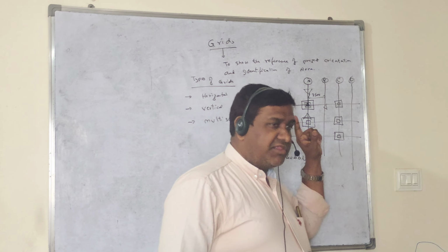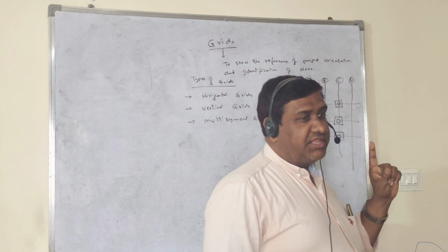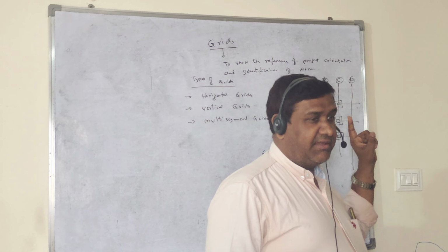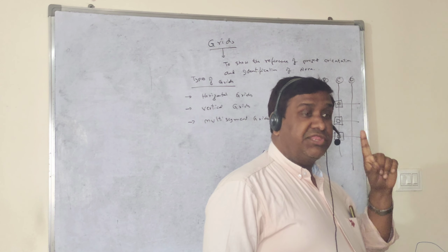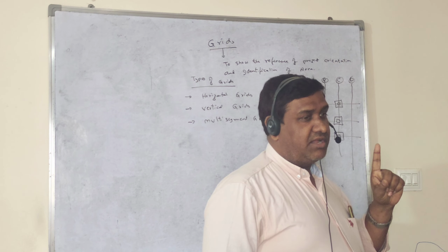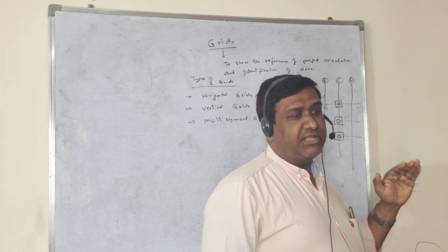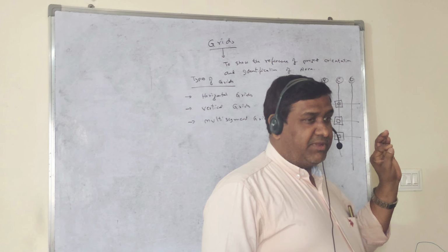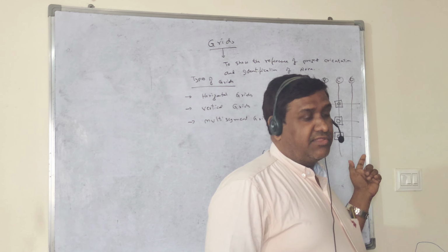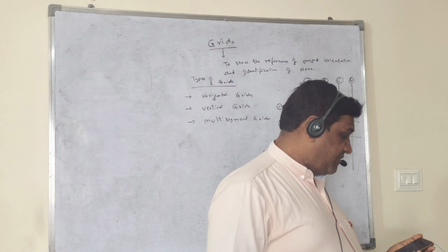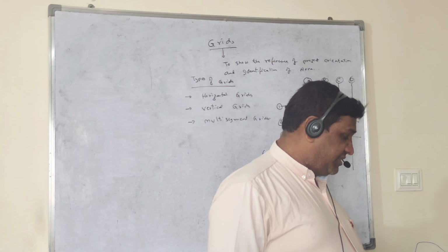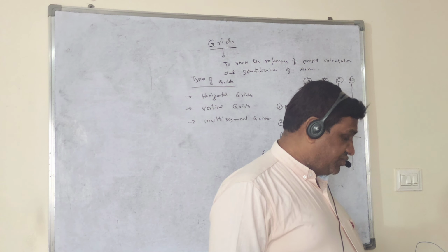And just remember, once you have placed a grid, the name of the grid, like A, B, C, D, whatever is in the bubbles, is the name. The name is not going to repeat, because each and every grid has a unique name, only one. It will never repeat. If you try to make it repeat, Revit is not going to place that grid. So one grid, one time, that's all. It will never come 2-3 times. Okay, remember. So while placing the grid, you have to remember that it should be only one.